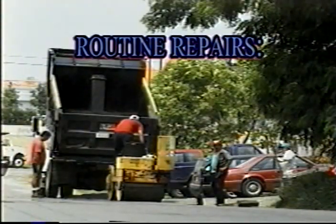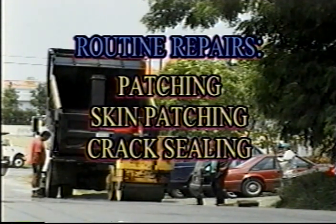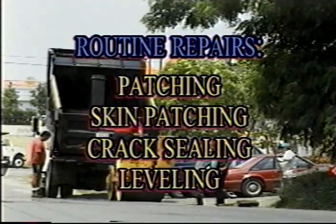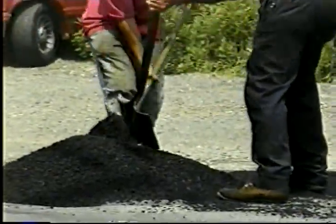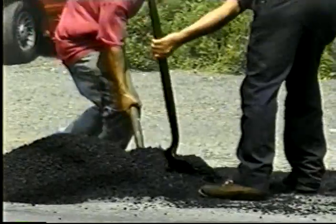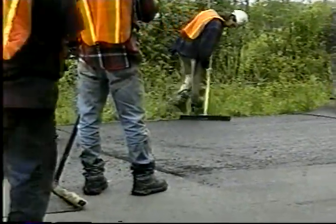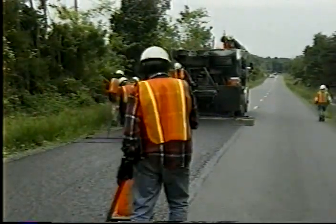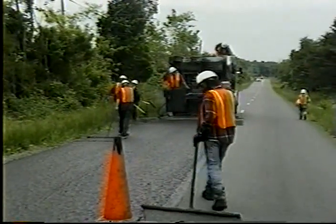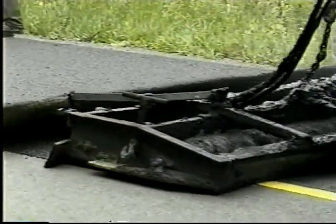Routine repairs, such as full or partial depth patching, skin patching, crack sealing, and leveling, must be made promptly to reduce the need for more extensive repairs later. In addition to performing maintenance at the right time, the proper type of maintenance must also be performed. Most seals add little, if any, structural strength to the pavement. As the name implies, sealing pavement seals the surface to protect the pavement from deterioration and penetration of water. Thus, seals must be applied before the pavement loses its structural strength.